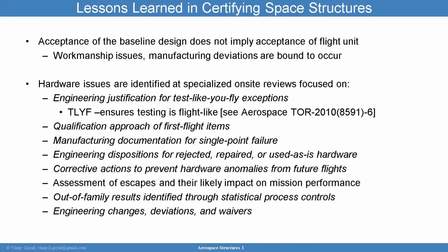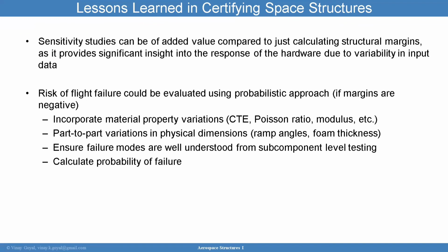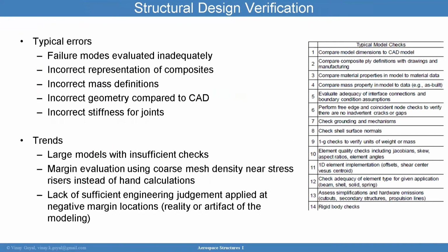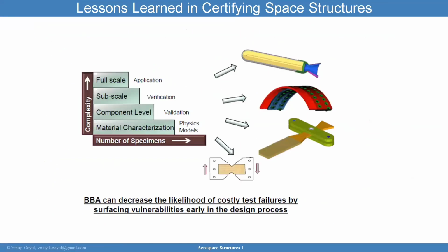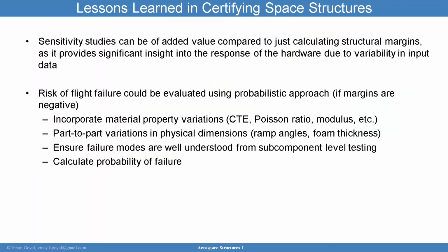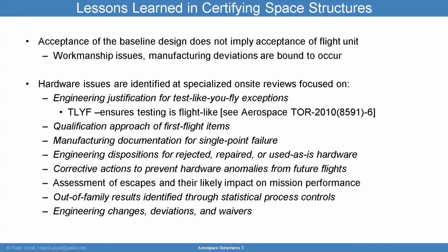I really want to talk about how important it is to understand that this is a design verification that we're talking about, all this, even the testing, the building block approach, all that. But we also need to make sure that the hardware has been correctly built. Acceptance of the baseline design, verifying the design, does not mean that the flight unit is good to go. You have to verify for workmanship issues. Manufacturing deviations are bound to occur.